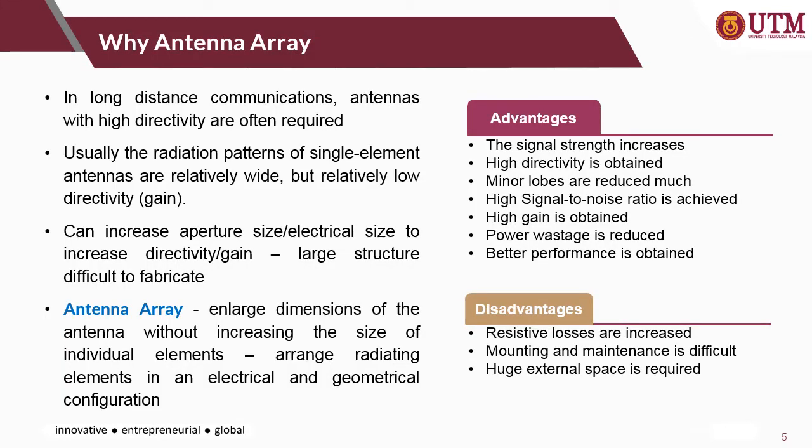Okay, so why is an antenna array needed? Why don't we just use a single element antenna design? For long distance communication, we need an antenna with high directivity. One example of a high directivity antenna is the horn antenna, which usually has a bigger aperture size, right?